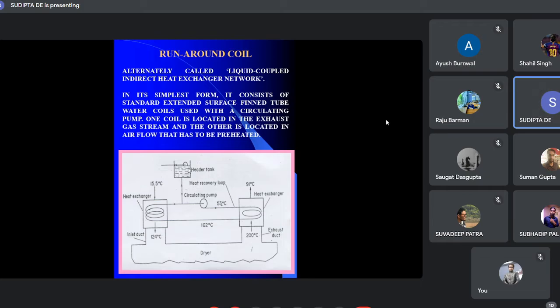So exchanging heat between these two different temperature fluids available at a smaller distance will be very much effective for the waste heat recovery purpose. But obviously the most critical part here is the working fluid which will be used for this purpose. It needs to flow with lesser pressure drop, and simultaneously there is not much scope of heat exchange in this process without extended heat transfer surface.